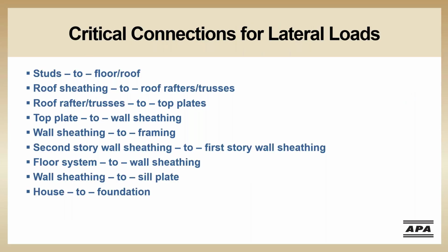Now that you understand what a load path is, how braced walls work, what can happen to a house when there is a load path failure, and exactly how a wind load moves through a home, the common details you see every day when you're out on the job site should make more sense. All of the connections discussed today are critical to ensuring that our homes can withstand the loads that are applied to them on even just a typical windy day. But during high wind events, these connections can be the difference between a home that remains standing and is able to protect the occupants and their possessions and a home that does not.